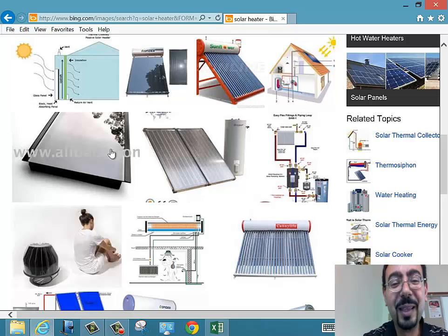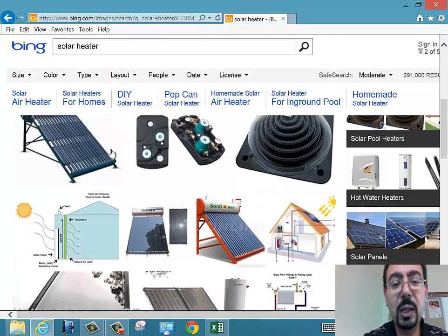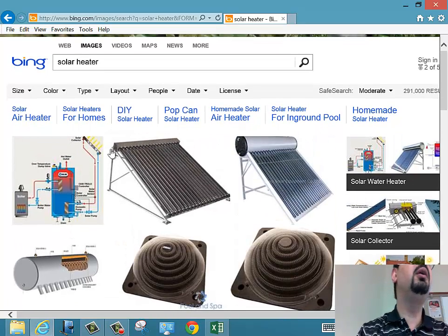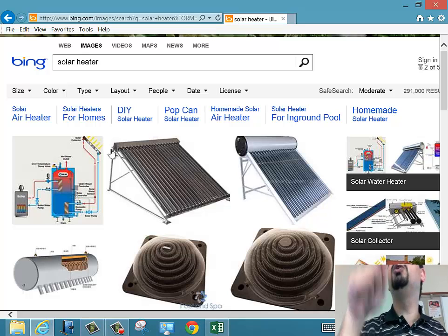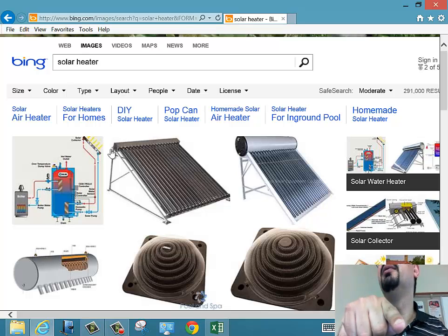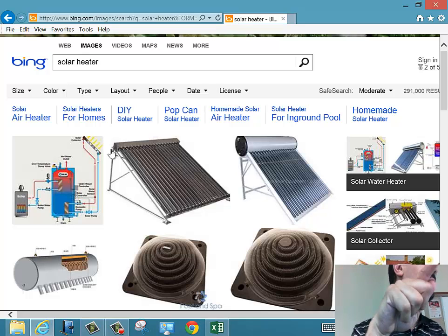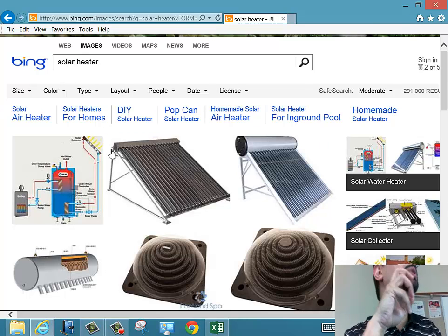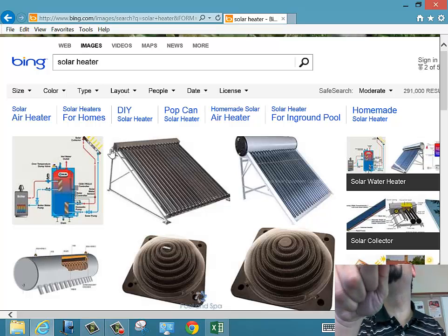But anyway, this surface is great because it has alpha really high, since it's black. It will absorb like crazy, but it will also radiate like crazy, and so it could end up heating the tree nearby. You don't want this. So they have a special selective coating, a special material that makes alpha really high but epsilon very small.